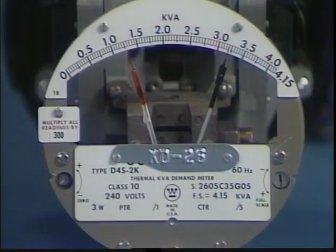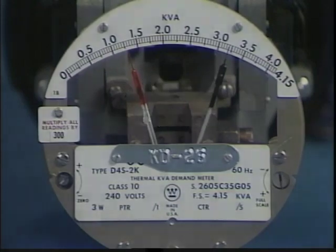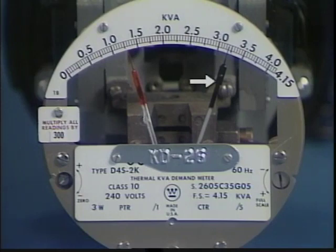Another method of metering demand is the lagged method. This method is related to the response of thermal demand registers and to electronic registers that have been programmed for a lagged response. Like the mechanical demand register that we just looked at, the thermal demand register also has a pointer and a pusher arm.